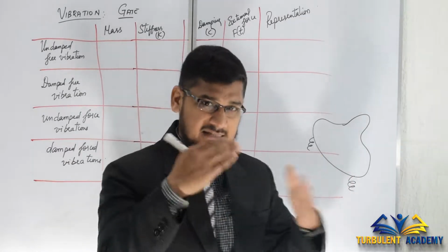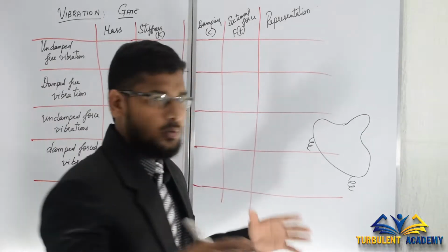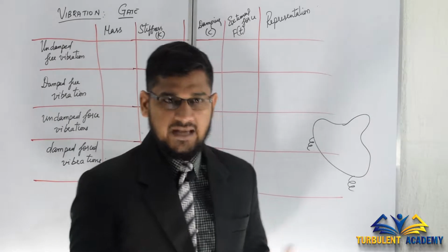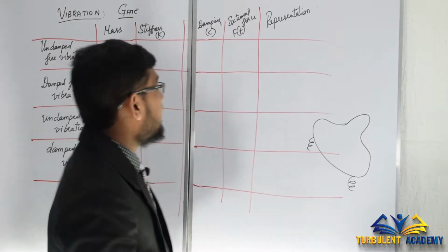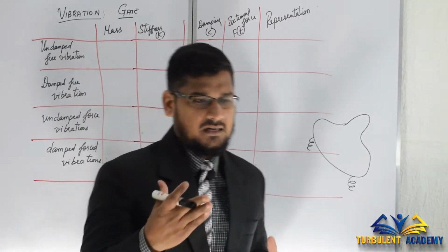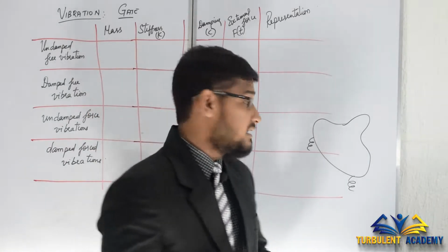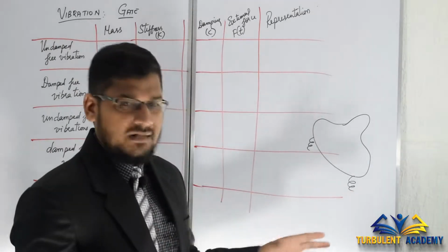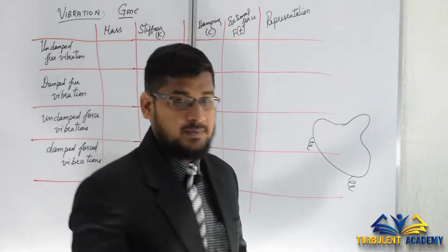A damper just reduces the oscillation to as much extent as it can. Now in modern-day two-wheelers and bikes, we can't experience this kind of thing because they have a damper. What we call a damper is mostly a piston cylinder arrangement, which gives more sense to understand a damper. For normal springs, this is the oscillation, that this seat will go up and down. That's what we experience, right?